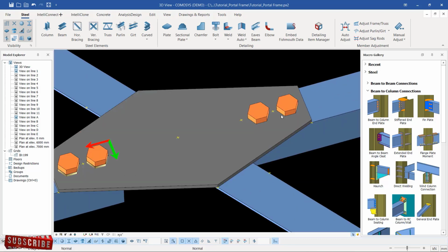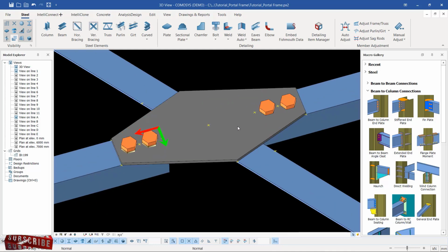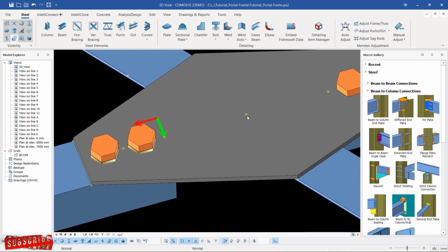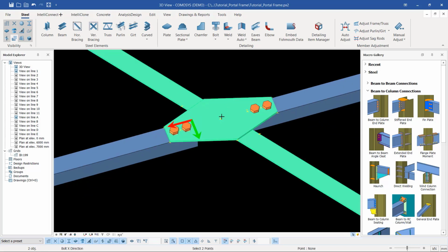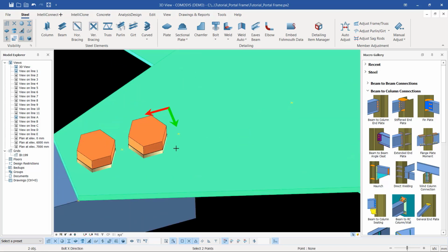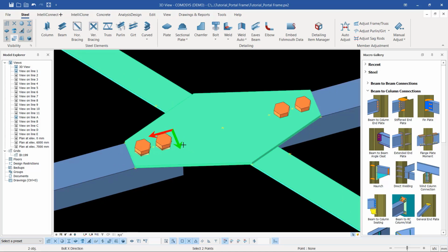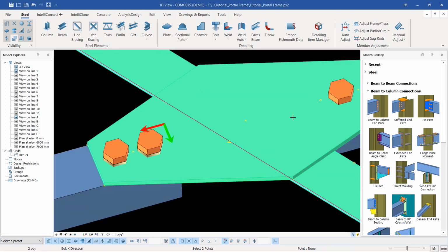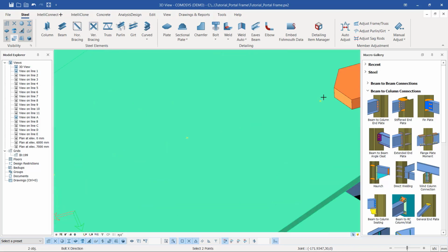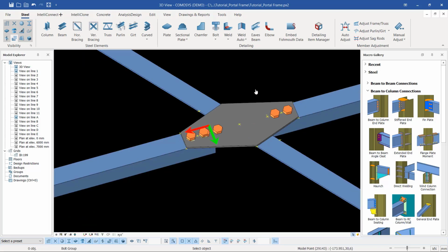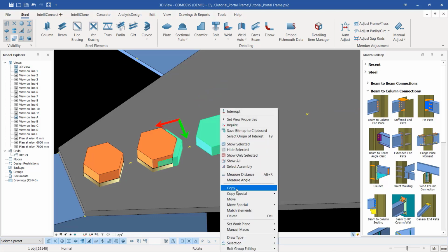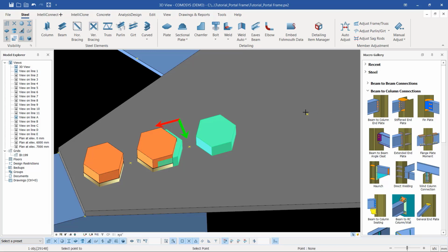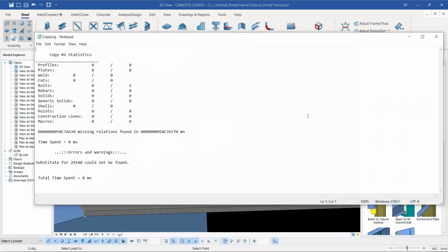Now we've created a bolt right there. Now we want to add another bolt in the middle here, so we'll come to bolt, select this plate and that, right click, and this time round we want to snap on this spot, on that spot, and snap on this particular spot. Let me just zoom closer, and you have that place in that member on the spot. So just right click on it. Let's try copy, and you can place that one right there.